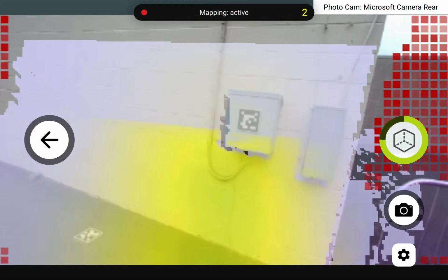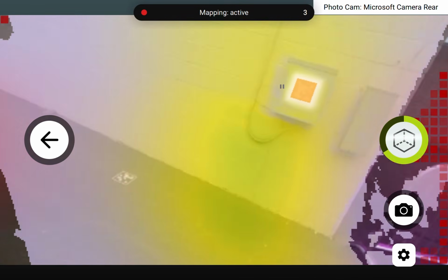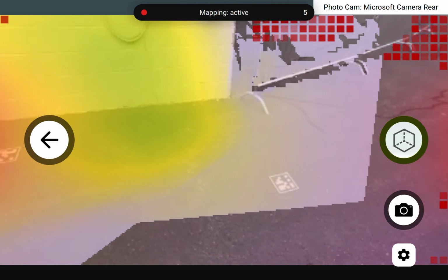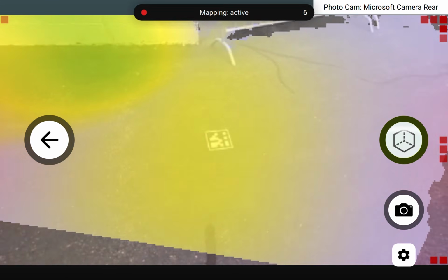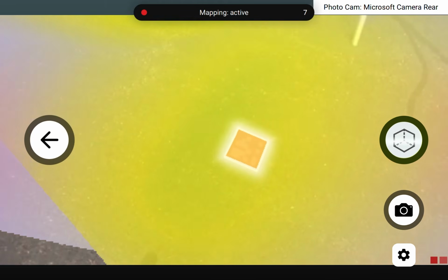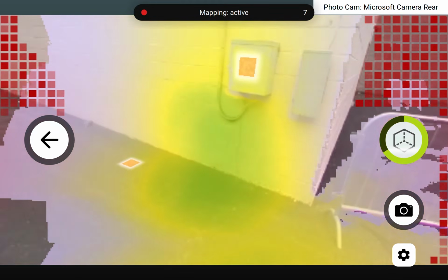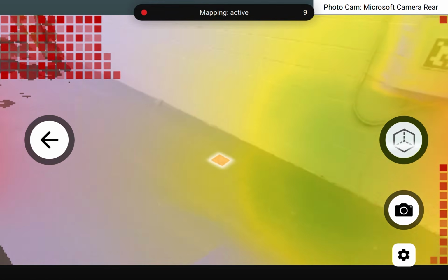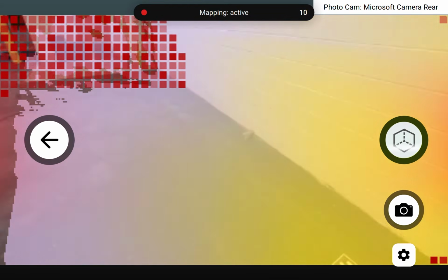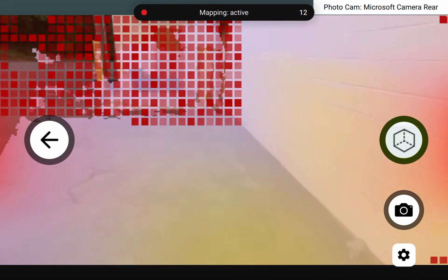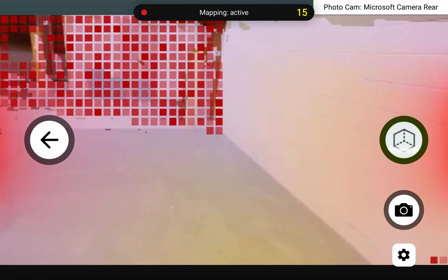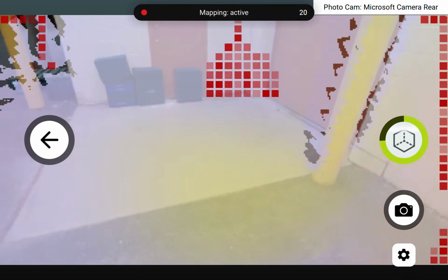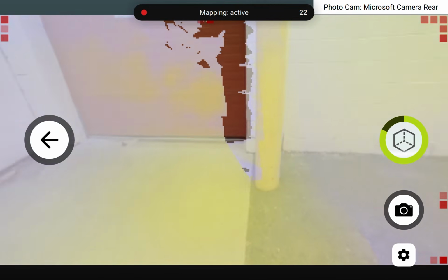And so we're now live, capturing a color 3D point cloud data set of everything we point the device at. You'll notice the green and yellow on your screen. That is real-time feedback on the quality of the points you're capturing, as well as the orange markers showing that these April tags have been recognized by Scan3D. The green and yellow is an overall quality report of each point based on angle, distance, time on target, reflectivity, etc.